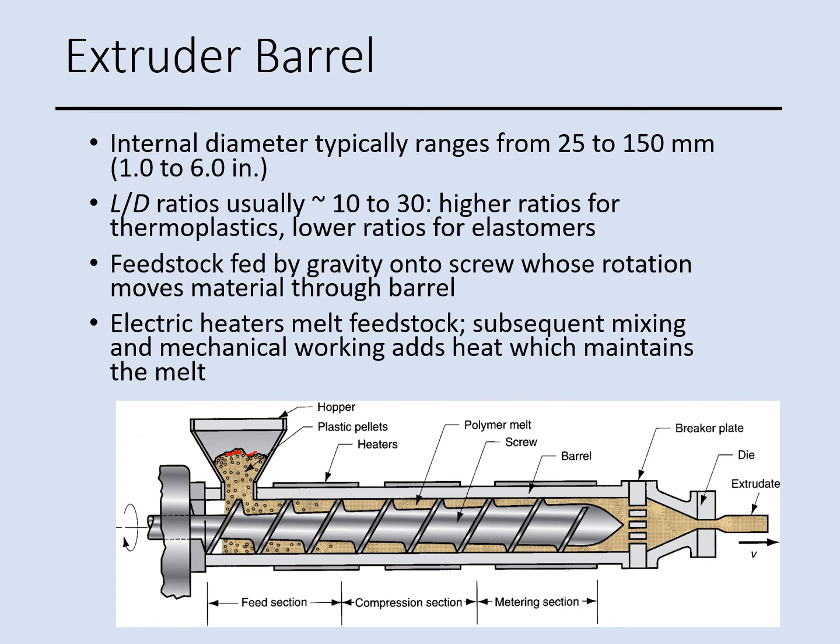In this picture, as you see, we have pellets in the hopper, and that is going to be moved toward the screw by the gravity force. And here we have a heater that melts the feedstock, and this screw pushes the material toward the die orifice.